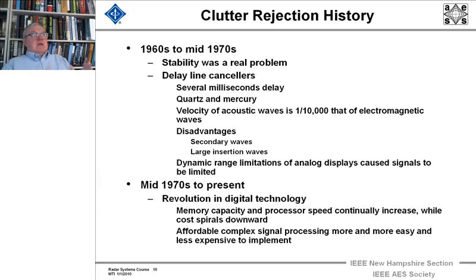You could drop it way down. Quartz delay lines used polygons of quartz that had reflected signals, where there'd be an input transducer, the wave would go over and there'd be a partially bent surface so that the wave would go back and forth and back and forth acoustically and then finally out. And it was more stationary.